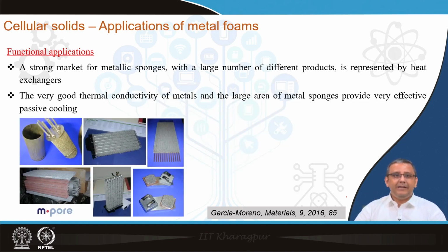Now, one very important application for metal foams is as heat exchanger materials. As you can see here, these heat exchangers are extremely important for many modern applications, typically for electronic components and also in many other functions. For heat exchanger applications, you need some fundamental properties. One thing is that the material should have a high surface area, because a high surface area gives you good heat transfer, and the material should also have a high thermal conductivity, and good permeability is also a very important factor.